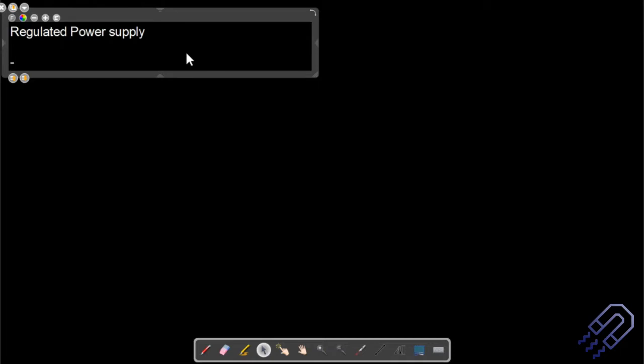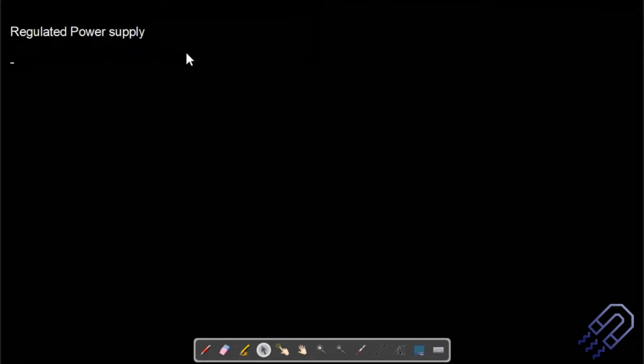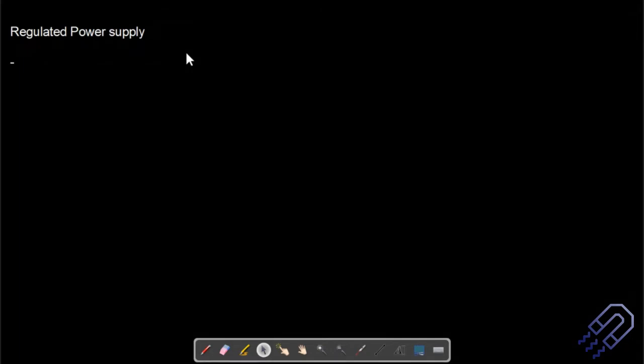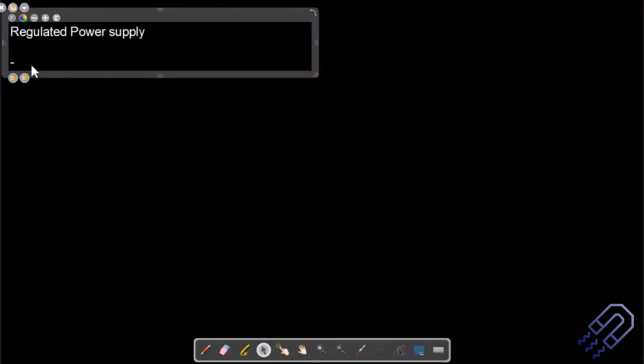So in general, if you're going to get AC to DC, you use a transformer. After that, you use some diode system, and then you get a rectification. It might be a full wave rectifier or a half wave rectifier. But after that, you get the output, and the output is never pure DC. For that, we have to use two additional circuits, and this is what we are going to look into now. So maybe I can start with writing for revision.